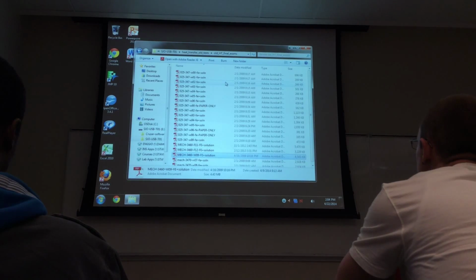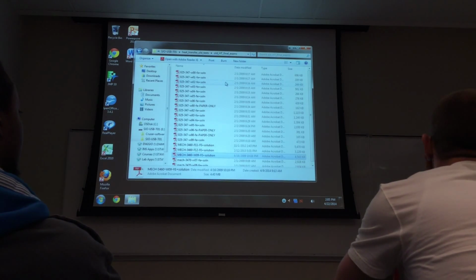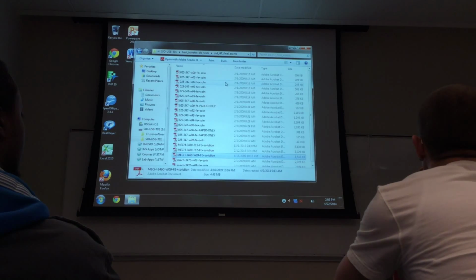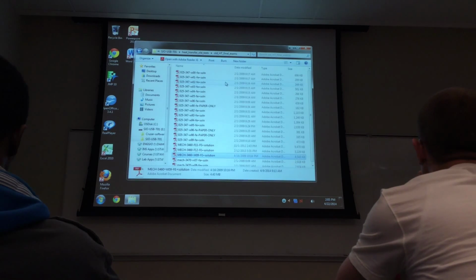Then it says show the velocity profile u of y is parabolic and has the form u of y equals 3/2 u_m times 1 minus y squared over (a/2) squared. Now, how do you get that? You have to set up a coordinate system, and fluid mechanics textbooks either put the coordinate system at the bottom or in the center. So is a the half height, or what's the plate spacing? The full plate spacing? Okay, so then let's do it this way.